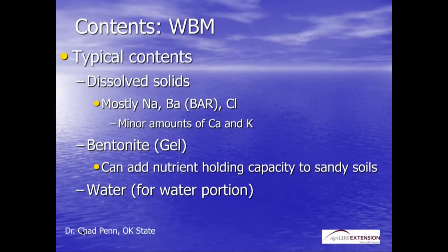Contents of the two different things. So this is a water-based. It's got a lot of what we call dissolved solids. It's got a lot of sodium in it, and sodium is one of the major problems that we have with this produced water. The primary reason we have the problem with the sodium is that when we get a certain amount of it into the soil, it has a tendency to disperse the soil. And once we get dispersion of the clay particles and the organic matter, that seals the pore